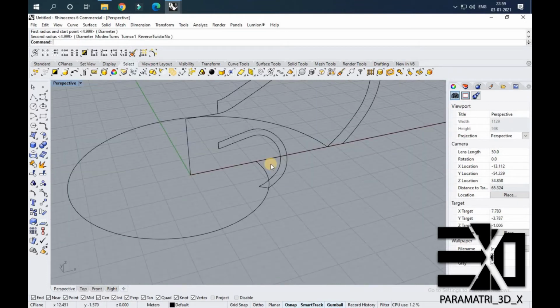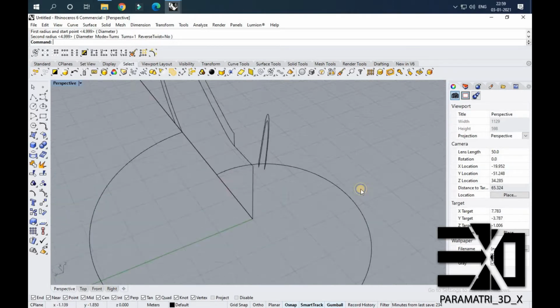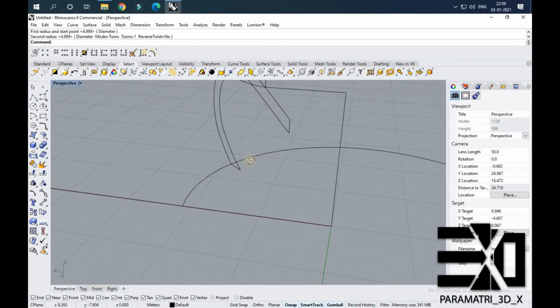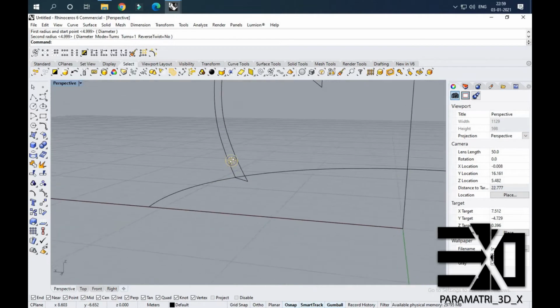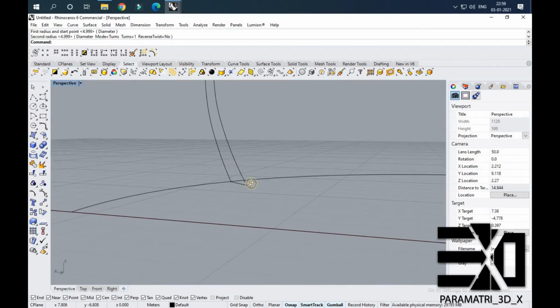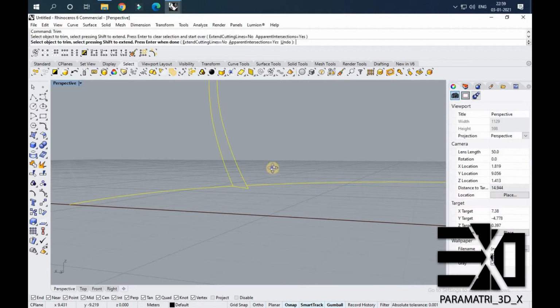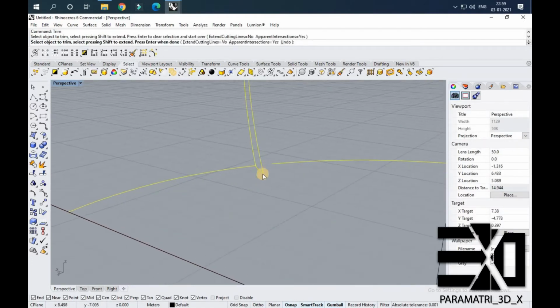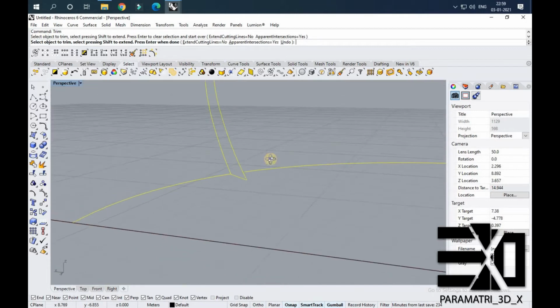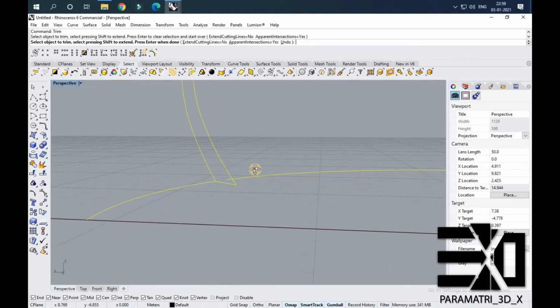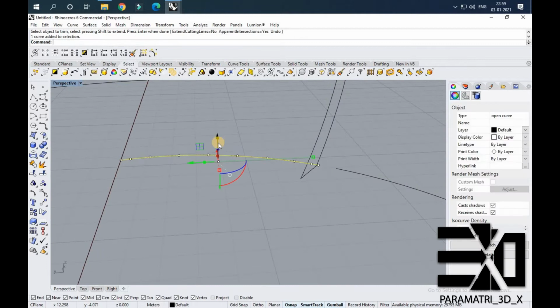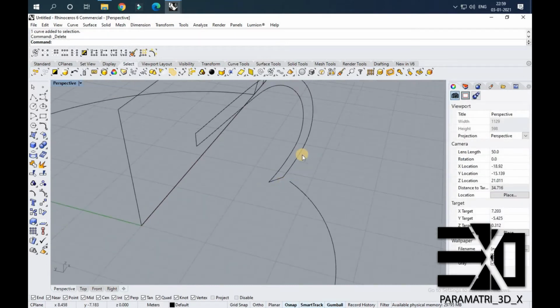So in Rhino, if you want to trim a curve, it's not compulsory that the lines should always have physical contact. You can trim the lines when they also have a visual contact. So in this, the line is having a visual contact. These two lines are not physically touched, but they visually touch in this angle. So I'm trimming with the help of this method, which is a really useful method.